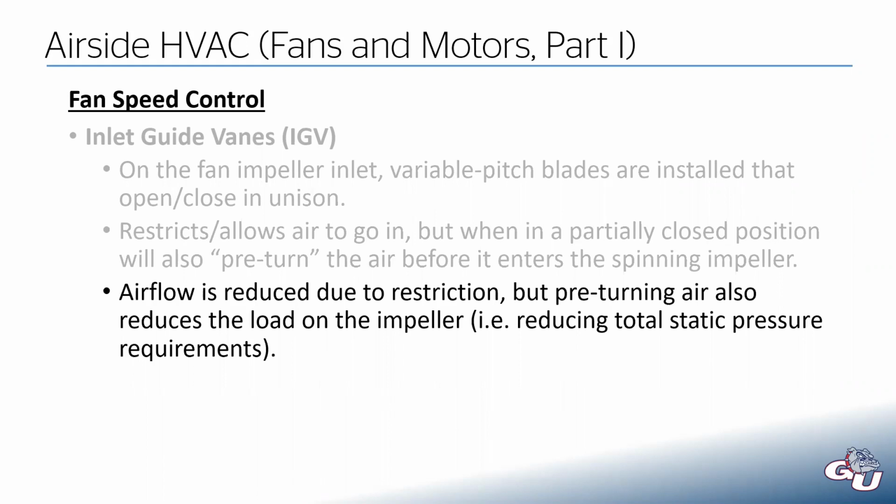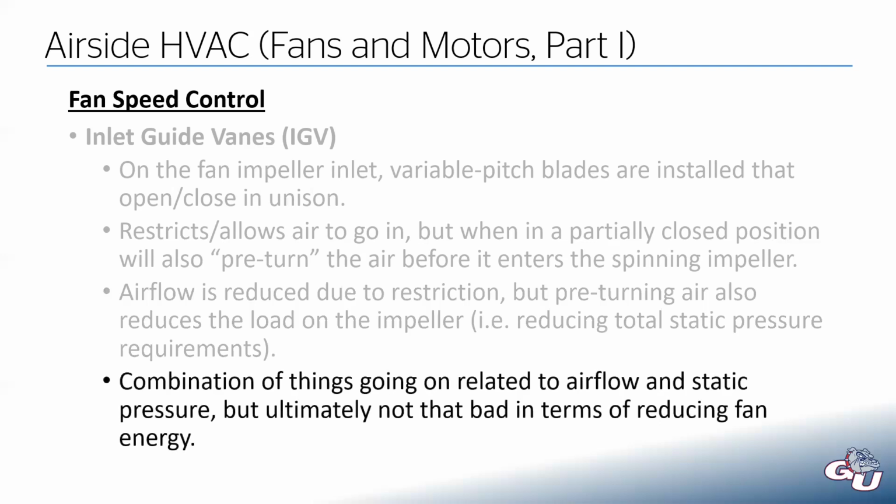And by doing that, that reduces the load on the impeller by reducing the total static pressure requirements. So it's a combination of things. We're reducing airflow, but we're also reducing static pressure. And at the end of the day, it's actually not terrible in terms of energy savings. It's not the best, but it's certainly much better than the discharge air damper.